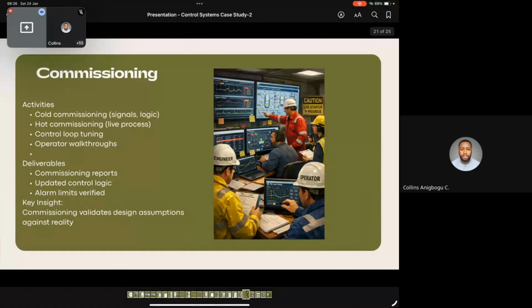And then when you get into the commissioning activities, before these commissioning activities, during the detailed design, you have developed documents that you are going to use for commissioning. And even part of the detailed design is the training requirements for the operators and maintenance people that will run the plant. So you can see the detailed design is a massive, massive activity, and it is very, very critical, right? So you do this commissioning, and it follows these steps.